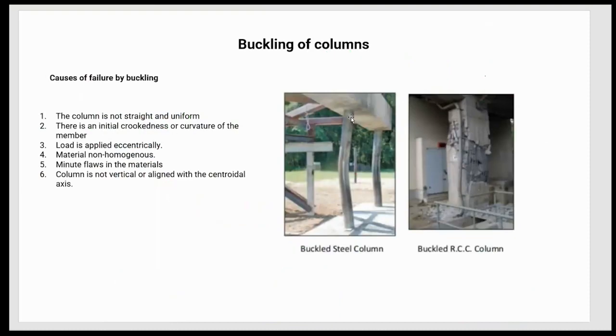So you can see here, coming back to this column, it buckled, most probably because the load applied overcame the crippling load of the column, and then it buckled. This is the natural way columns deform. There is no other natural way. Well, there might be other natural ways, but this is the most likely way for a column to fail. And why might they fail?